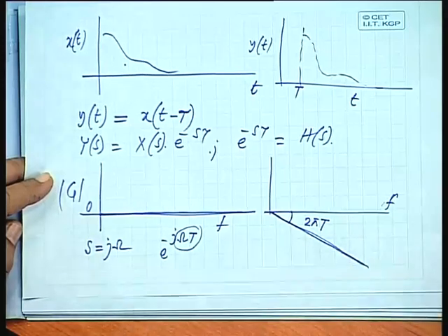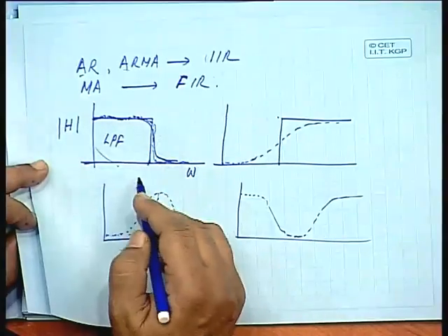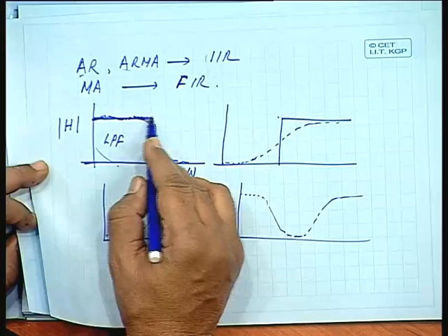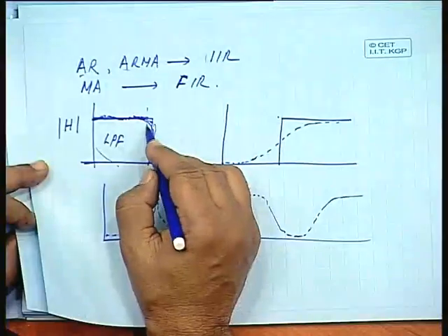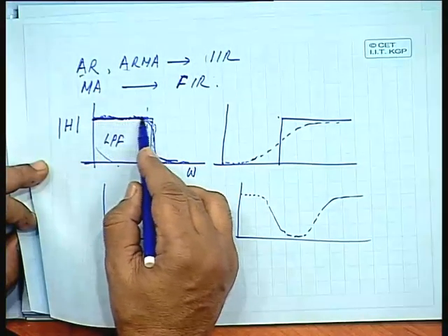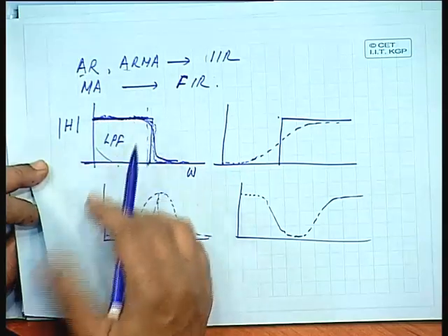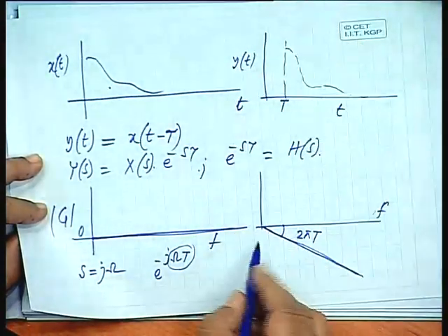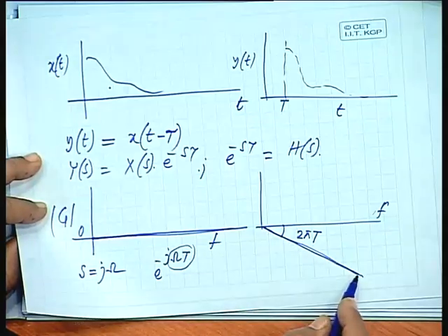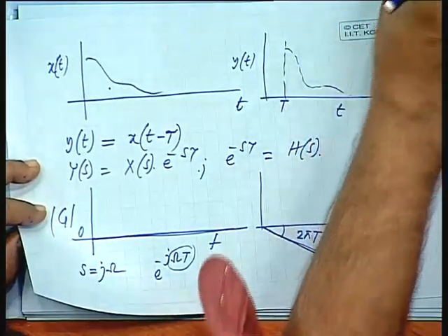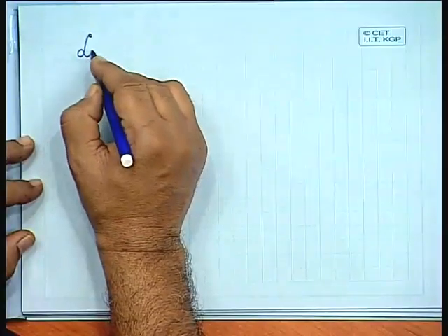For example, when we transmit speech signals, for different frequencies, if the gain is varying, if it is a filter, say a low pass filter like this, the gain is constant if my frequency is limited to this band, and if I can maintain the gain more or less constant, and I have to design a filter where phase is linearly changing with frequency, then only my voice will be faithfully represented, otherwise there will be distortion. Now, this is known as linear phase characteristics.